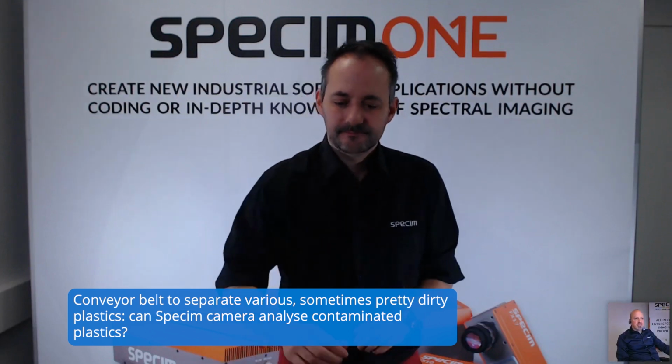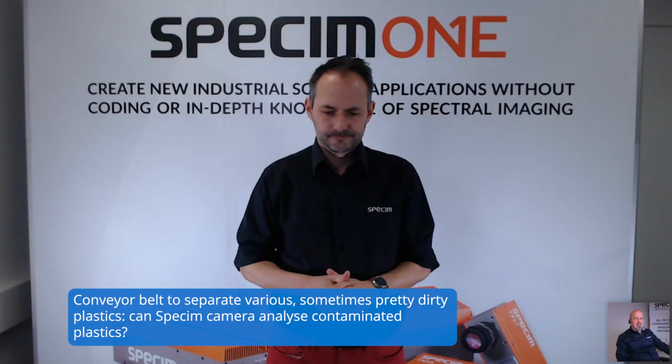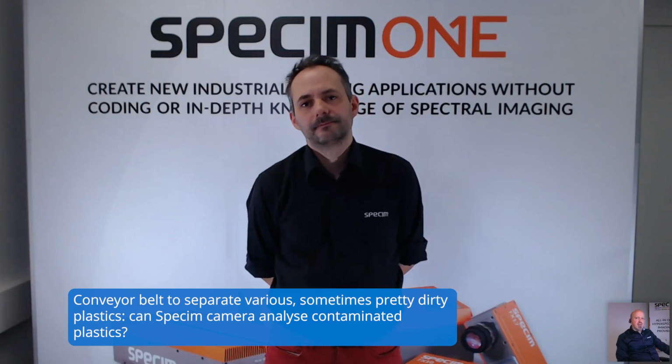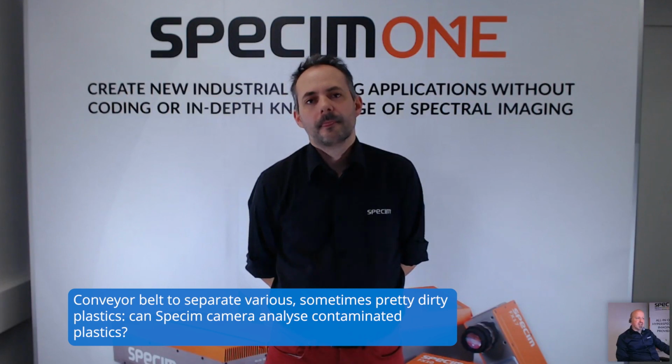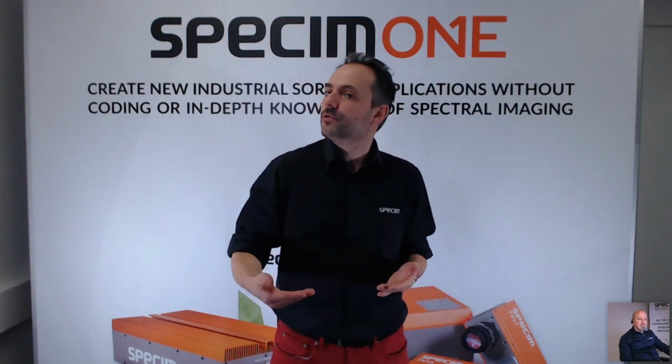As you already know, I'm sure, when the plastic is very contaminated, you won't see the plastic anymore, because we don't do X-ray. We need to remind people that hyperspectral imaging is a surface measurement method, especially for waste recycling. If you have a lot of dirt, the camera cannot necessarily see through the dirt. So that's one thing.